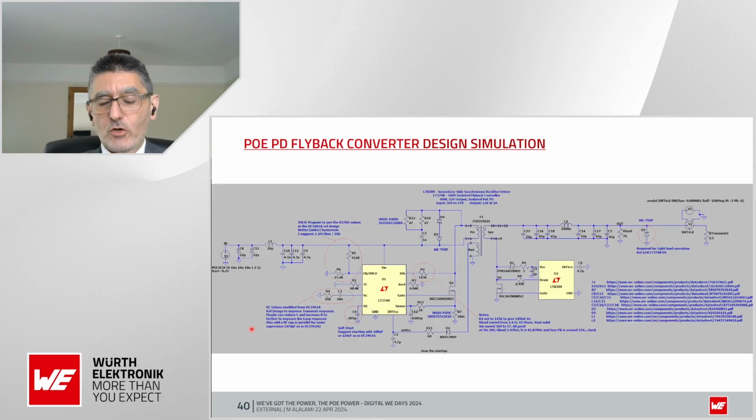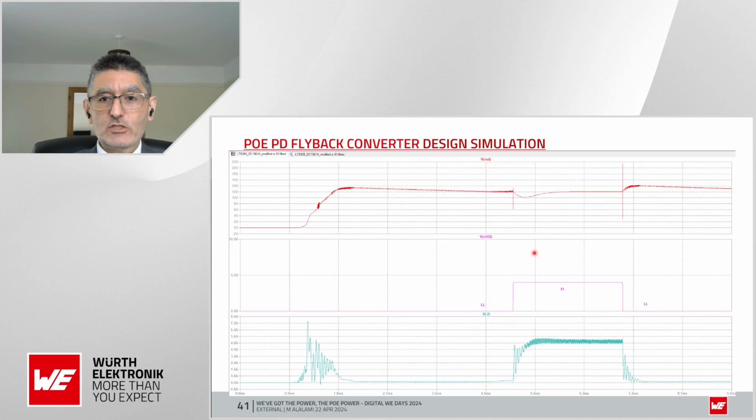I'll finish off by showing just a couple of the slides with the final simulation that we've done for this system using LT Spice again. So that's the new transformer, the updated snubber circuit, the filter for the sense signal, the under voltage lockout, the compensation network as well changed, as well as the input and output filtering also included in the simulation.